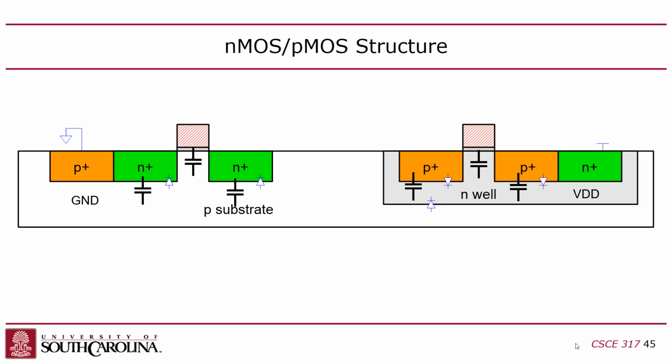If it does, you're in big trouble. That's called latch up, and that'll fry your chip. Latch up is when you get current flowing from the source and drain down into the substrate, right? Latch up can be the result of a badly designed chip. In the case of a PMOS, and I didn't show you this yet, but obviously the PMOS is different. The problem is that when you make a chip, the whole chip has the same substrate. It's the wafer. You make a wafer, right? The wafer is the substrate of the chip.